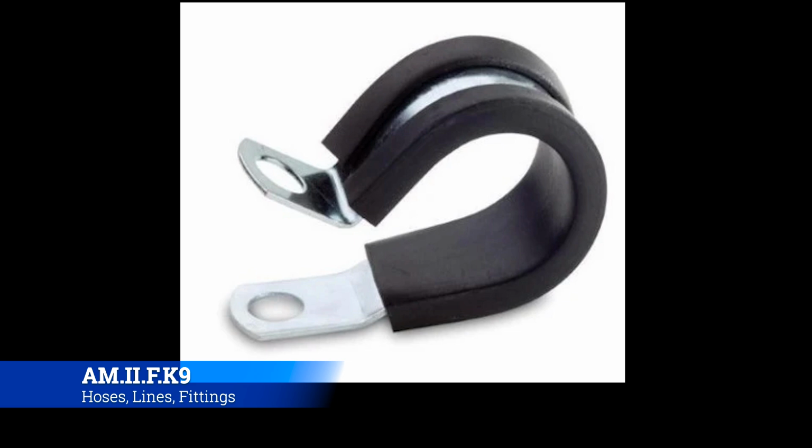And if a hose is rubbing up against something, you can clamp one thing off to, say, an engine mount, and then on the other side you have your Adel clamp that actually holds the hose itself. And so you can customize a lot of this to get the right routing for your particular aircraft, and that's perfectly okay. That is a very common practice throughout all of aviation: heavy commercial, military, GA. Everybody uses these things.